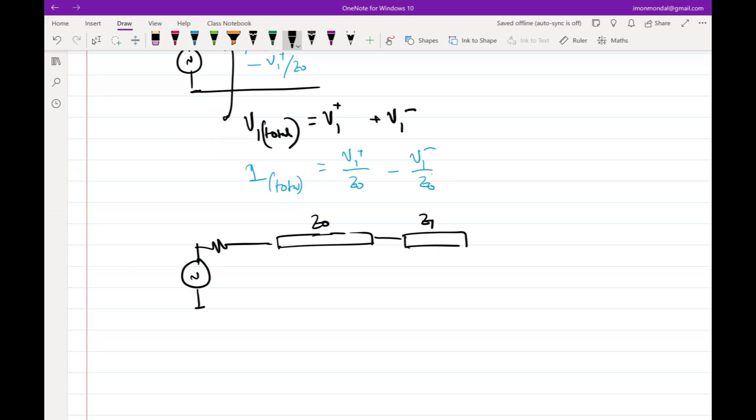So if you are talking about a forward going wave, the looking-in impedance is still Z0 because it doesn't know what is at the other end. The total impedance will be different, because whatever is coming back will depend upon what is getting reflected here, and that will be a function of Z1 or whatever is connected there. The impedance that we know of, by very definition, is what happens to a settled circuit. After everything has settled, at infinite time, the ratio of voltage and current is the way we define steady state impedance. The steady state impedance will be a function of Z0, Z1, whatever is connected.